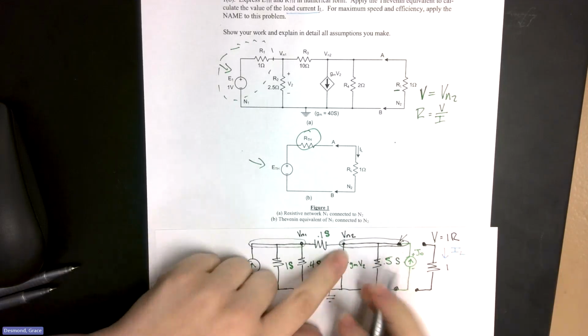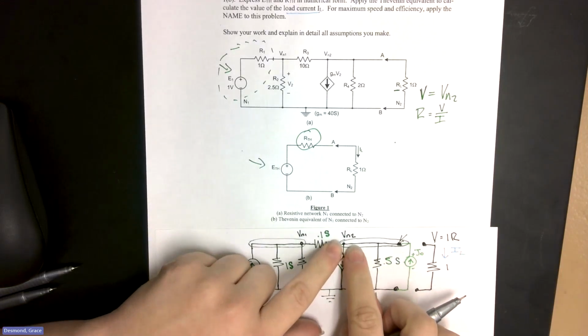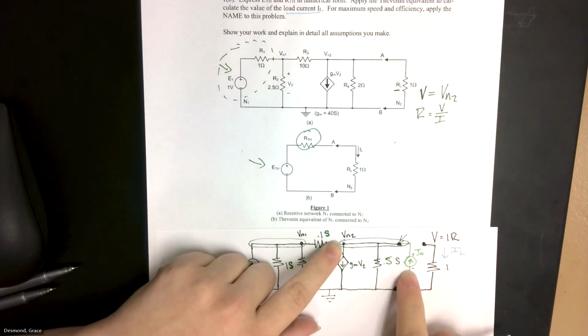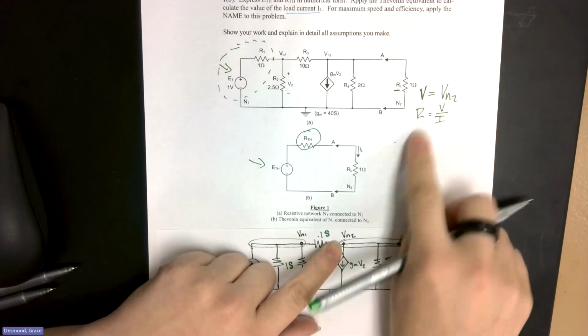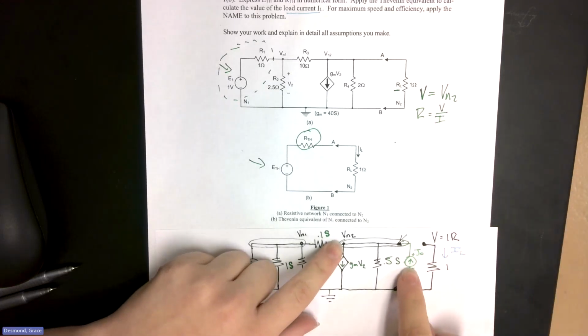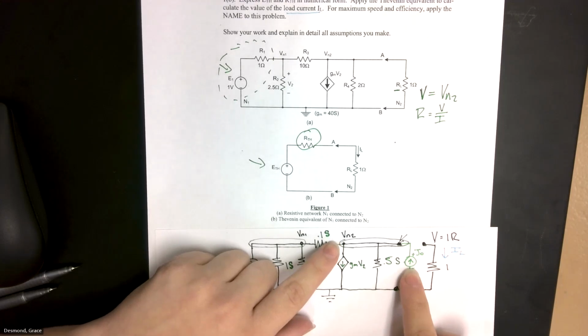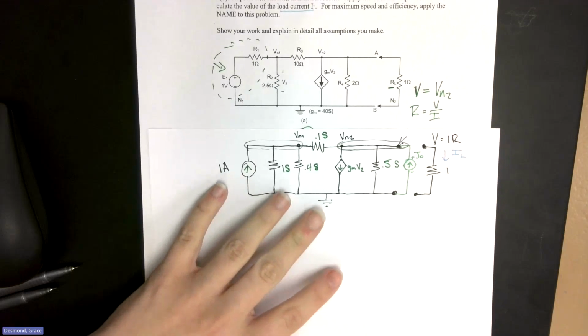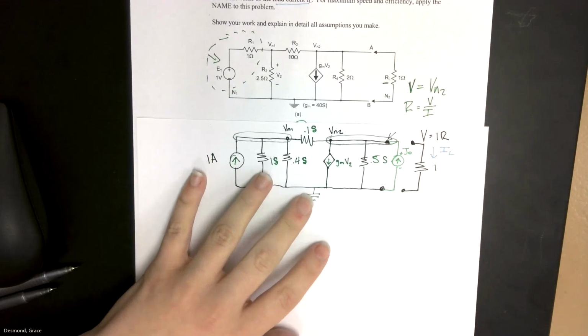So we already said we know what the node voltage is. It's VN2. But since we're putting a current there, can we just say that the resistance is that node voltage divided by whatever that current is? Apparently one, right? Yeah, so since we're choosing to divide by 1, it's just VN2. So we add a current source here to manipulate Ohm's law and use that to get our Thevenins.